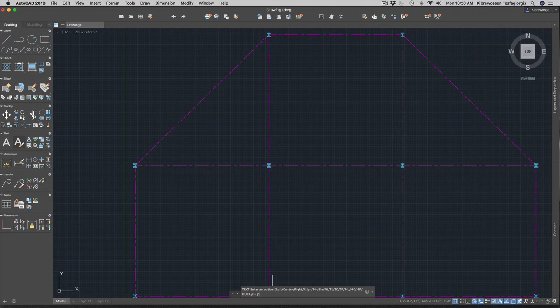If you saw those texts, they are located at middle center. To represent middle center, you type MC. You see, there is a list of names given here. I'm going to go with middle center. Then I pick the point, for instance, here is mine, and I click.